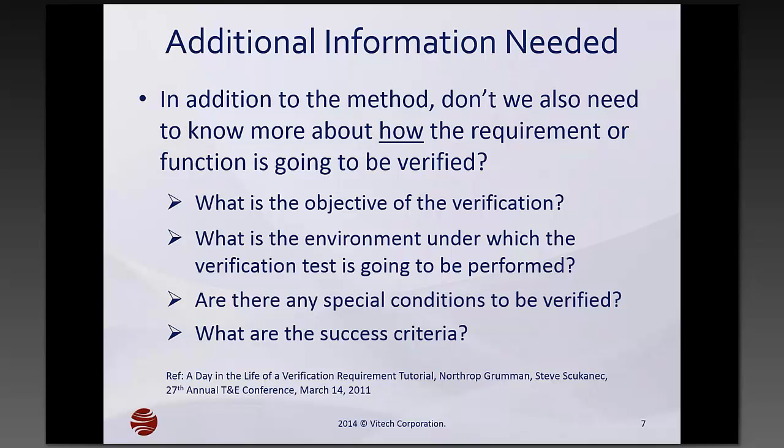I recently worked with a customer where they were working on a hydraulic system, and the hydraulic system was specified to operate between two pressure set points, let's say 800 and 1200 pounds. Their accumulator was set so that when it got to 800 pounds, the system charged back up to 1200 pounds, and that's the way the system operated. The reason the pressure was set at that level was because they needed to have enough force to close a particular set of valves within a certain time set point.